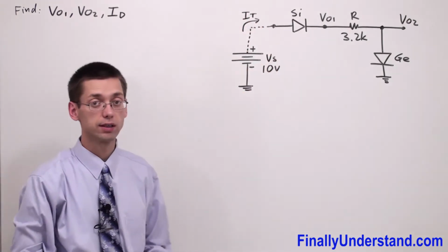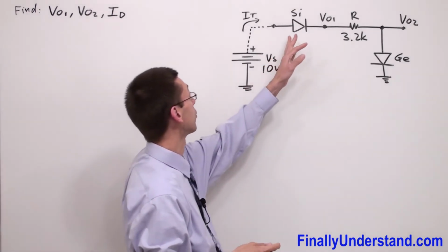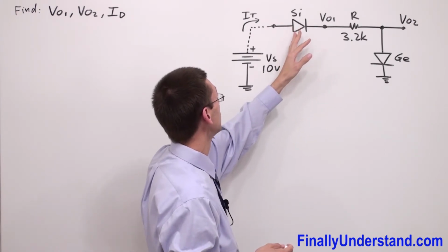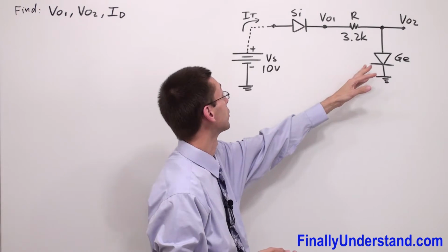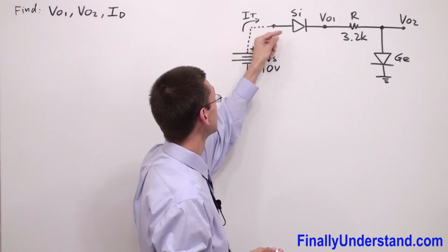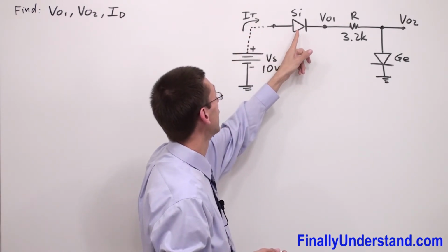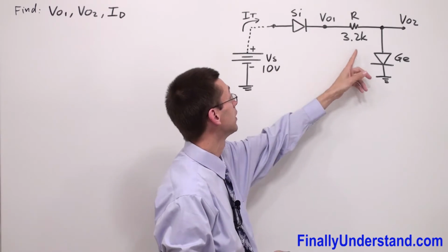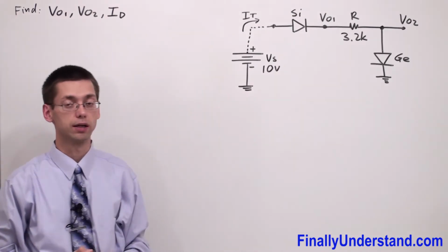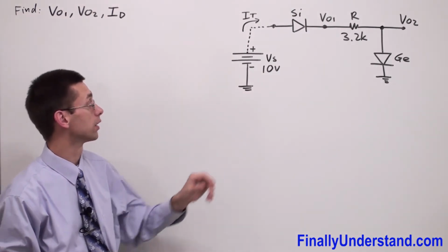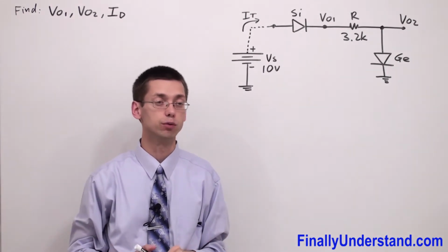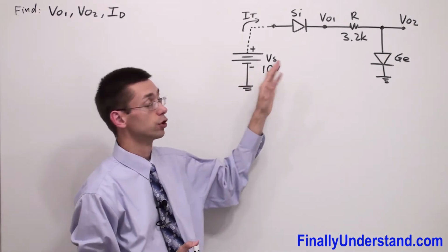Next, you're supposed to look at the direction of current, and at the direction of the arrowhead of the diode symbol. I mean the silicon diode and the germanium diode. Please notice that the arrow points in the same direction as the arrowhead of the silicon diode and the arrowhead of the germanium diode, and the voltage source is greater than, in this case, 1 volt, because 0.7 plus 0.3 is the minimum we're supposed to have in order to make this circuit work.